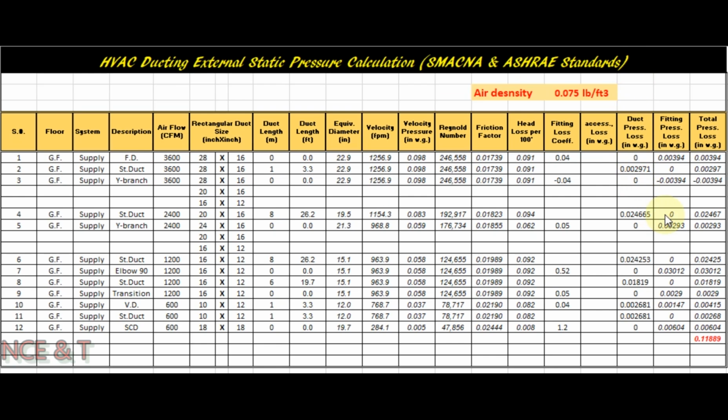After calculating the value of fitting and accessories loss coefficient, when we apply these values along with the duct basic information in this Excel sheet, it automatically calculates for us the value of total external static pressure for the duct.